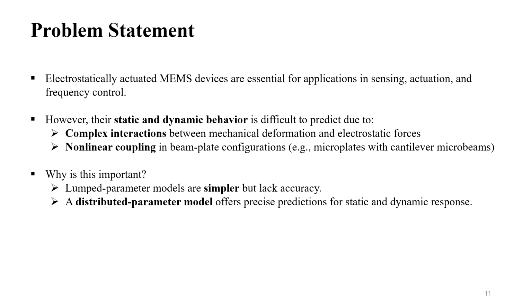Now, due to the promising experimental results of the sensor used by Dr. Ghumaim, we decided to produce an analytical model to further explore its static and dynamic behavior, which is difficult to predict due to 1. The complex interactions between mechanical deformation and electrostatic forces, and 2. The nonlinear coupling in beam plate configurations. We opted for a distributed parameter model over a lump parameter model because it offers more accurate and physically representative predictions.